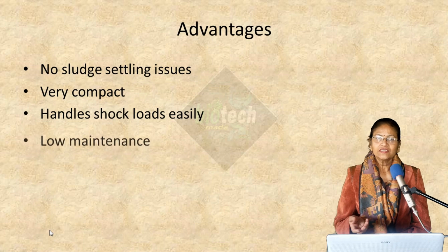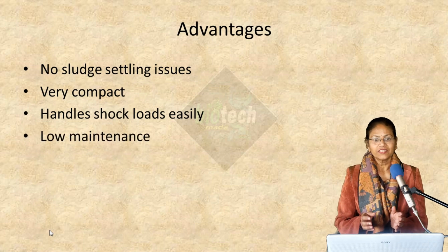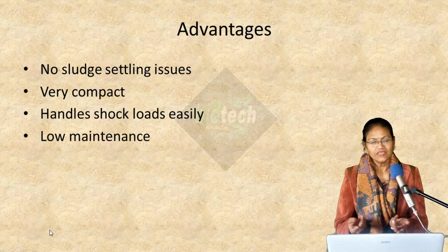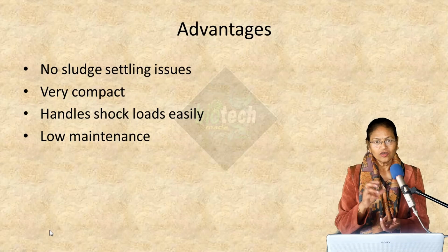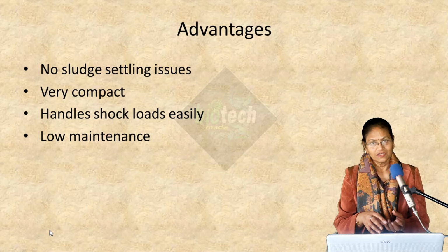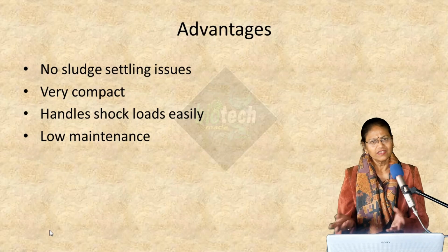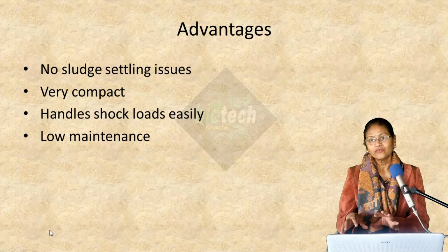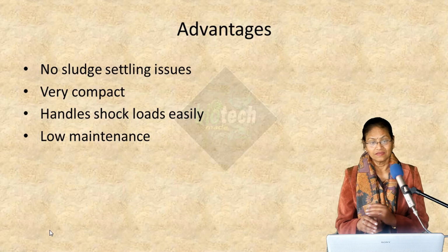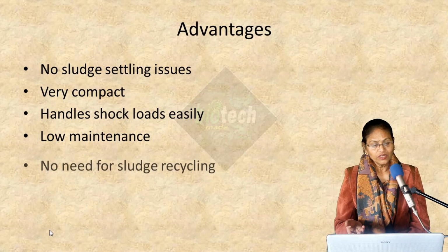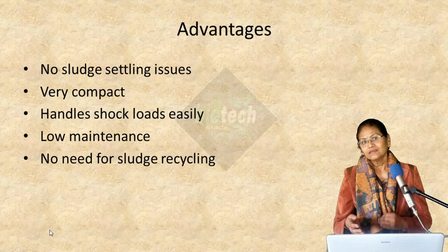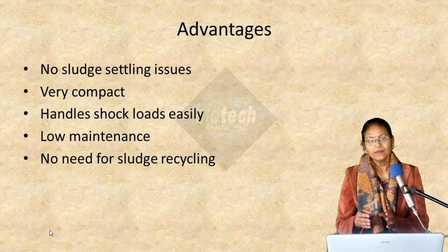And there is low maintenance because it is designed in such a way that we don't need to do anything. Even the sludge is not repumped mechanically. Everything happens automatically because this is a biofilm based system. So that's why it has low maintenance. And there is no need for sludge recycling as it was in the ASP.